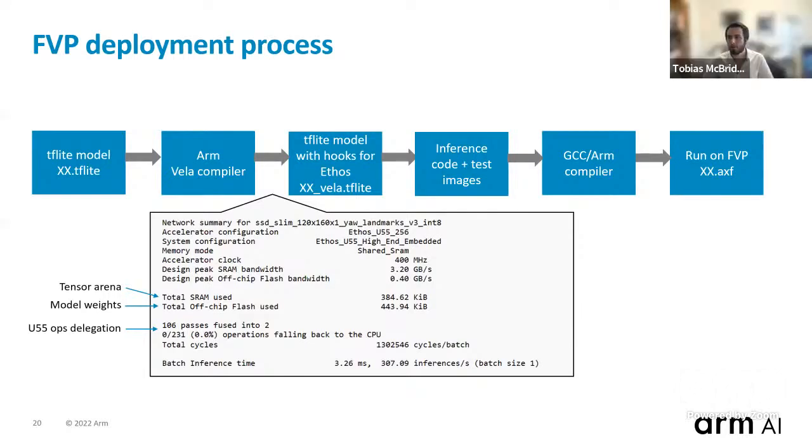And Henrik, flicking back to you, why did you choose what you did for the high efficiency clock speeds? So the clock speed for the high efficiency subsystem is the maximum clock speed for it. You can of course run it at a slower clock rate if you don't need to run it that fast. The reason that we went for that range is we wanted to make sure that even if you are running a part of an application that needs to be low power and power conscious, we still have enough performance in that subsystem to be able to execute that efficiently, right? Because you want to be able to finish the workload fast so you can go to sleep sooner. That's how you save the most amount of power. So that's what we were targeting.